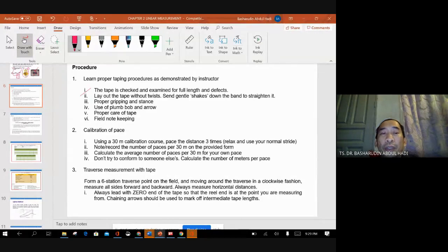It's short 10 meter, so you don't use that tape. Or maybe the tape is in good condition, but one of the screws on the cover has peeled off. You can see that there should be 4 screws on the cover, but today you can see just 3 screws. So don't use that tape because it gives you the wrong distance.